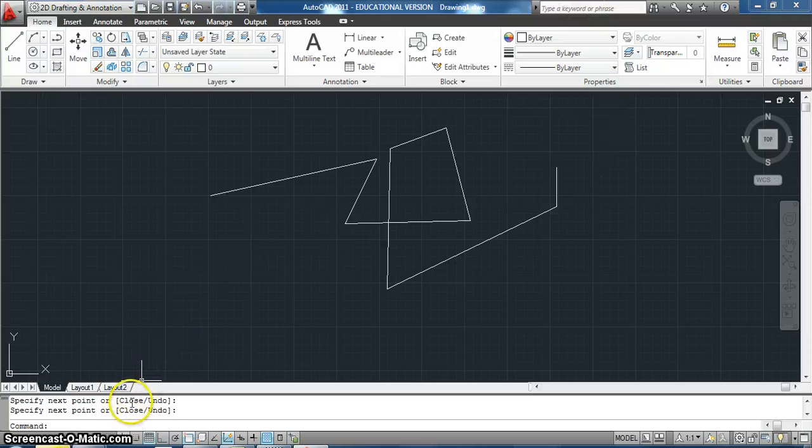So we're having a look at some of the ones that we use quite a bit down here. And first of all, we go to the snap mode. Now the snap mode will snap our line tool to a grid. You can see there that my cursor is jumping around and it's not smooth, and the reason that is because it's snapping onto a series of grids that are on the page.